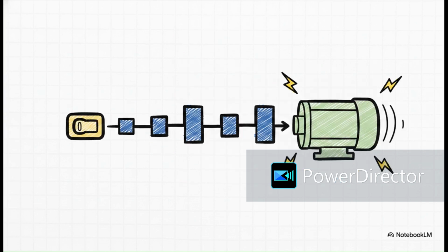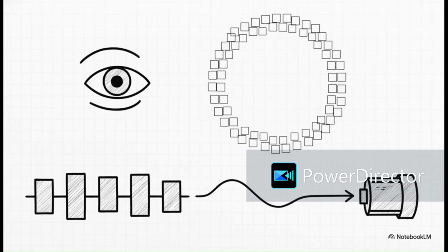But the reality of what the VFD is spitting out is completely different because the IGBT is a switch. It's strictly either on or off. It can't create a smooth curve. It continuously triggers these highly rapid, blocky square pulses. If you look at the raw voltage output of a VFD on an oscilloscope, it looks harsh, jagged, and honestly, kind of messy. So how on earth does a motor that craves a smooth wave operate on these harsh square pulses? This is exactly where you drop a killer analogy.